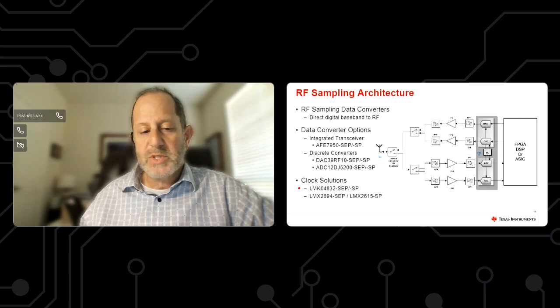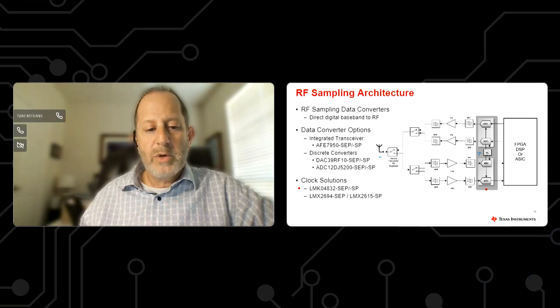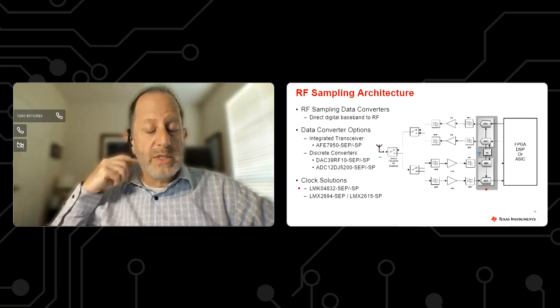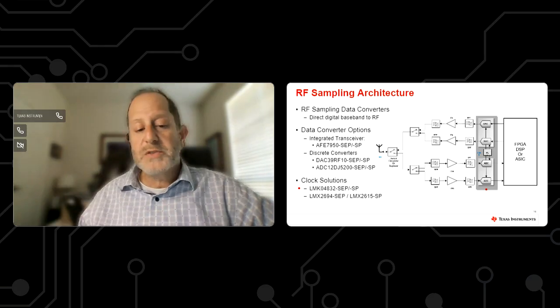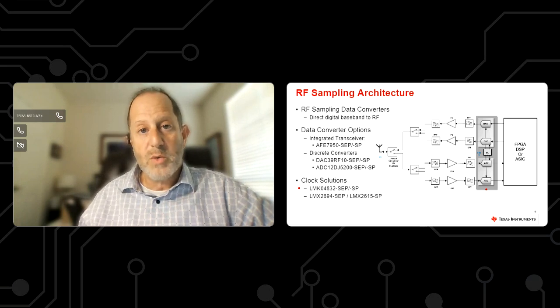And then for the high frequency sampling that's needed for the data converter itself, or if there's an up converter for an LO, we'll look at the LMX2694 and the LMX2615. These are space grade solutions that are high frequency RF synthesizers that can support the low phase noise requirement needed for those opportunities.